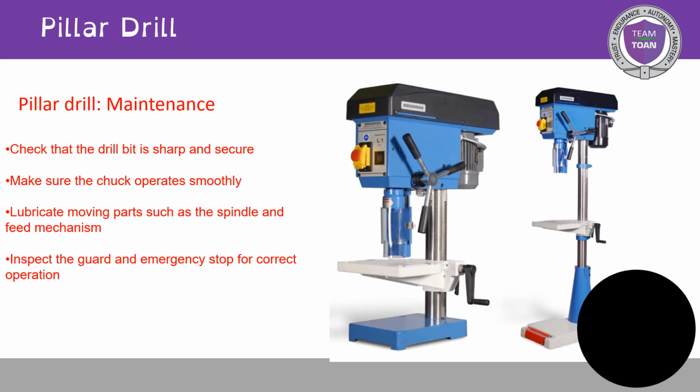Pillar drill, check that the drill bit is sharp and secure by tightening the chuck. Make sure that the chuck operates smoothly, lubricate moving parts such as the spindle and feed mechanism, and inspect the guard and emergency stop for correct operation.